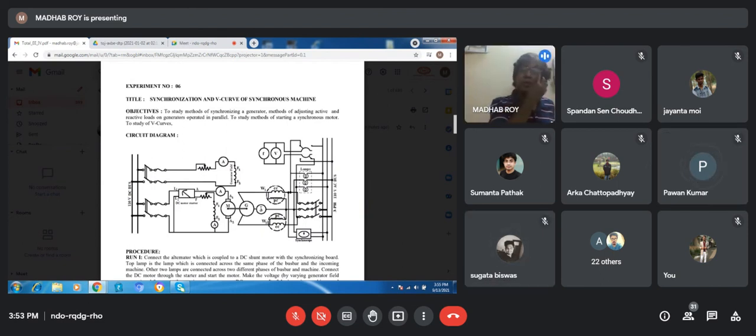Yes, sir. Okay. Now, the problem of the reluctance motor is that we are not having any power from the field side. Only power comes from the difference of reluctance, due to the salient pole. Basically, this type of motor works at a very low power factor, and that's why its output power is very low. So if we try loading this reluctance motor, you can do that.